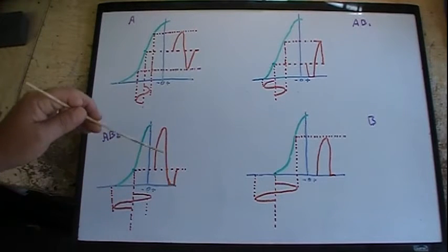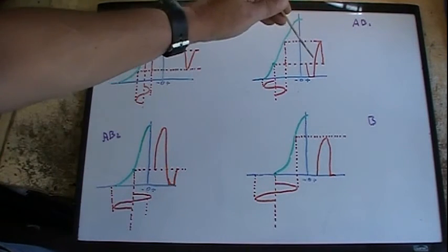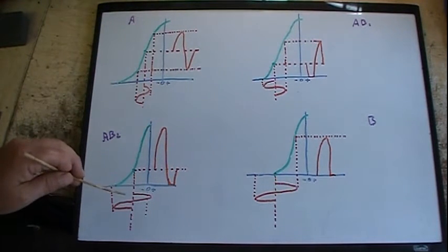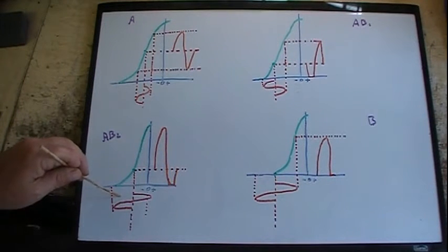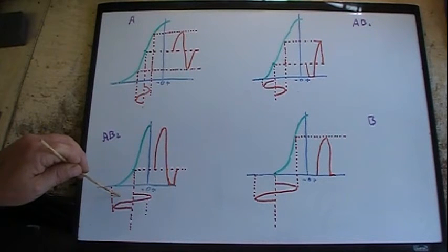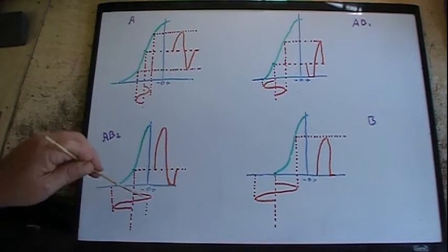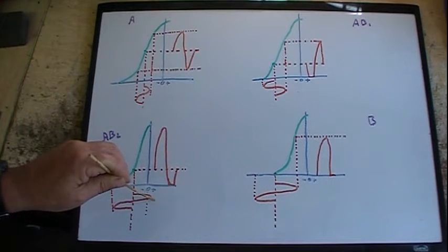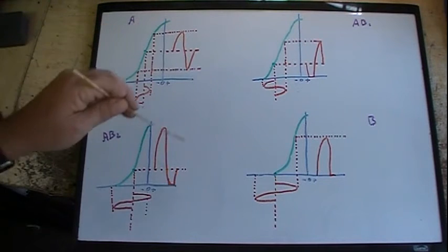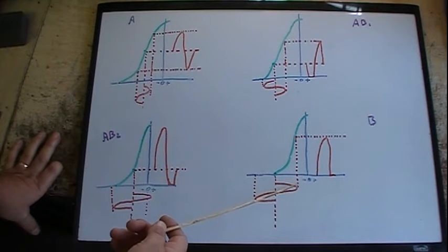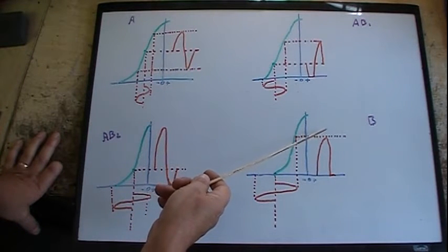I can do that. Or I can have the same operating point, in other words the same negative voltage, but, and this is what I was talking about with the preamp tube on that schematic, does it have the range to do it? If it's putting out a strong enough signal, peak to peak, when you adjust the volume level up, that can push this grid to positive, then the output is running AB2.